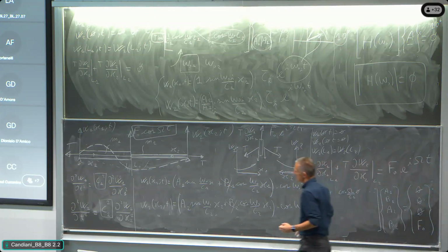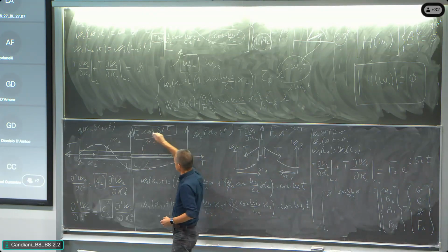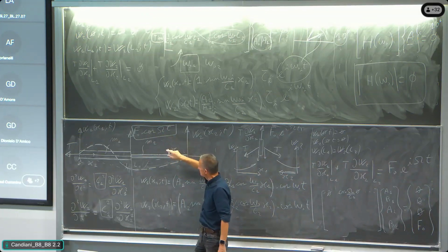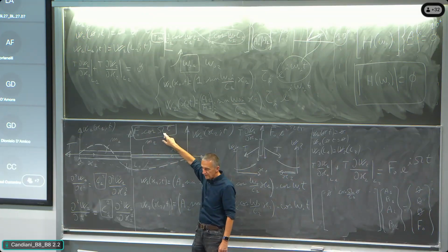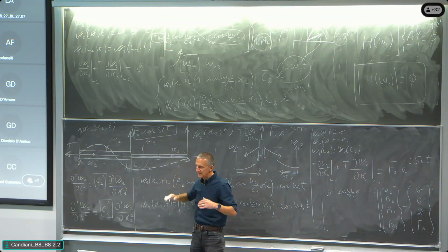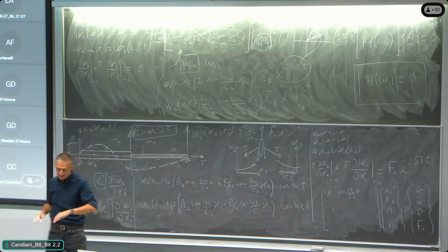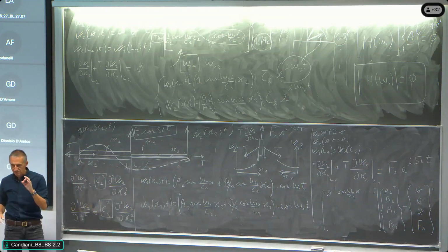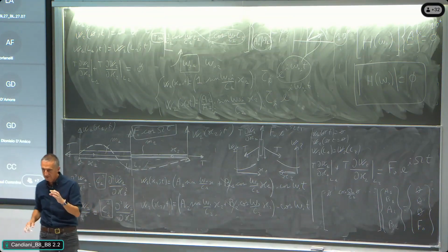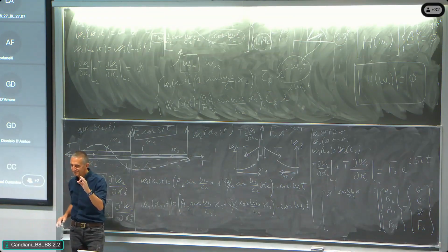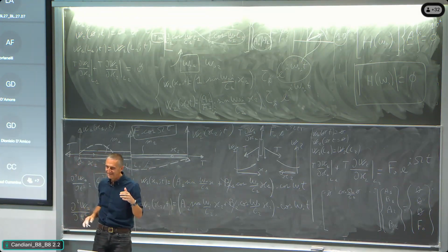So when we are exciting with a specific frequency omega, the system is answering with exactly the same omega. So we are putting this condition. To say it correctly in a formal way, this is true only when any other excitation coming from the initial condition has been cancelled.